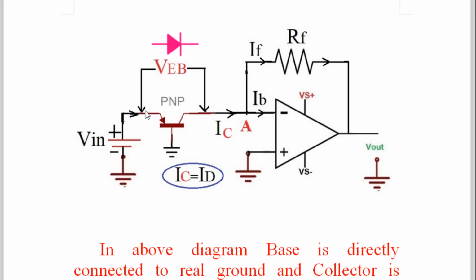So this will work as a PN junction diode, such that the p-type material is the anode, on the left hand side, and the n-type material is the cathode, on the right hand side. This is what we want in an anti-log amplifier. The diode should be here, whether it is a PN junction diode or a transdiode, but the anode of the diode should be on the left hand side and the cathode on the right hand side.